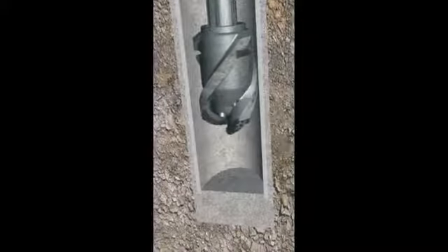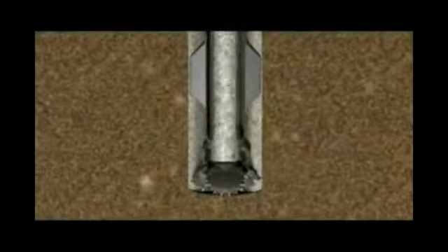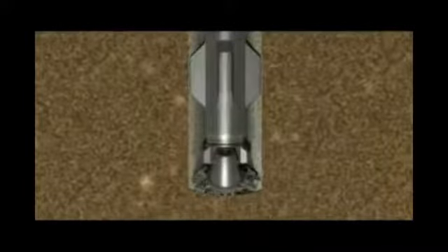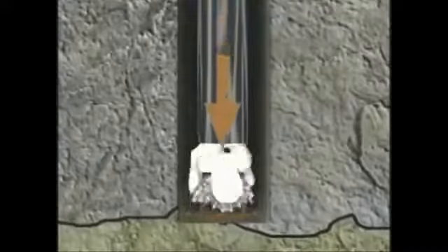Basically, within the rotating system, the drill bit turns, cutting the rock and making the hole. As the bit rotates, drilling fluid is forced down the drill pipe to jet nozzles in the drill bit as it cuts the rock. These jets of fluid clean the bottom of the hole of the rock debris from the rotating drill by moving the debris away from the bit and then up to the surface. The drill stem rotates the bit.